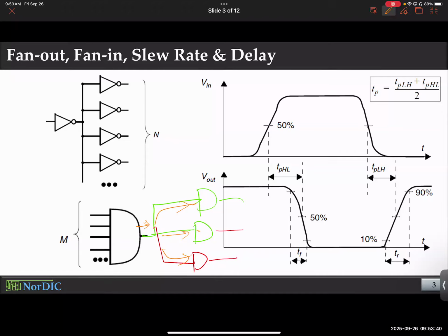Transistors. And what basically you're driving is the gate of the transistor. What is there at the gate of the transistor? Capacitors. Did I tell you that? Capacitors. So when you see a line getting to an input, imagine it's as if you're driving capacitors. All you're doing when you're driving something is charging up the gate capacitors. Now, when you have 3 branches, you have 1/3 the current. So you need almost triple, it's not linear, almost triple time, if not more, to charge up the same capacitor. Don't you think? Because the currents are getting distributed across multiple branches. So you need to provide current for longer.